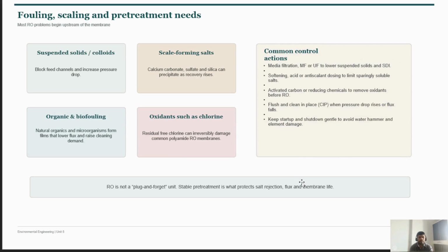Okay, the same problem in this also, the fouling and the scaling, will be there in any kind of membrane technology. The suspended solids can block the membrane pores. The scaling, because we are targeting the calcium carbonate, the salts which are present, the silica, sulfate, can form scaling onto that particular membrane. That is a physical scaling that can take place. So that problem will be there.